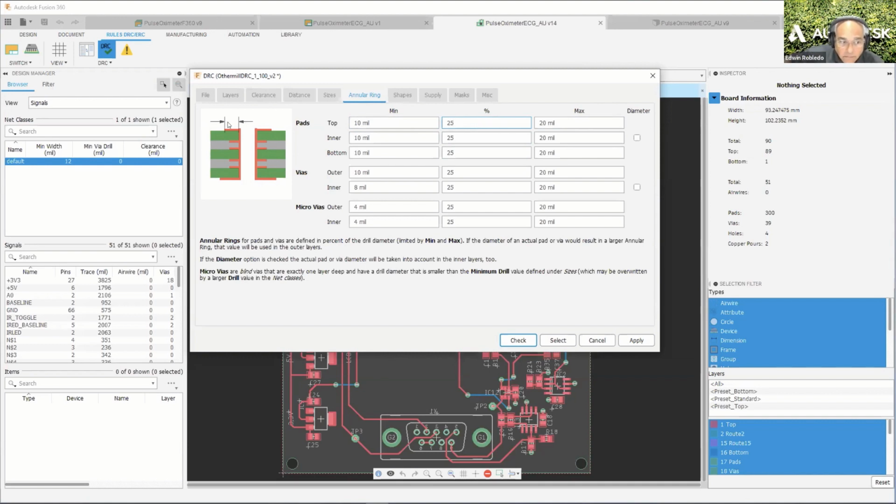Correct, because that drill, again, in the pictures, we always draw it perfectly centered, but there is a tolerance there. And if you look at a real board, you'll notice not all the drills are dead on. Depending on the board house, it might be a little bit or a lot sometimes. I've seen a lot of it on a couple of boards.